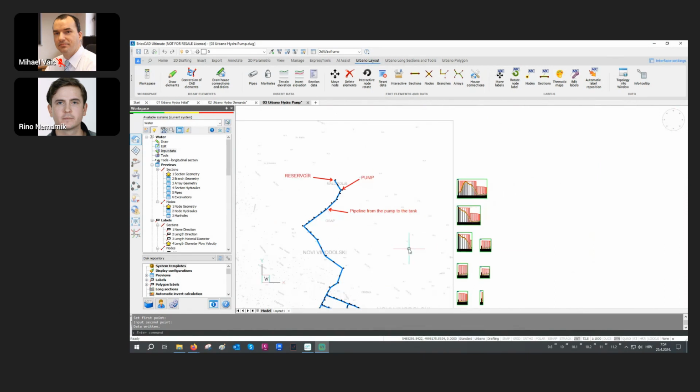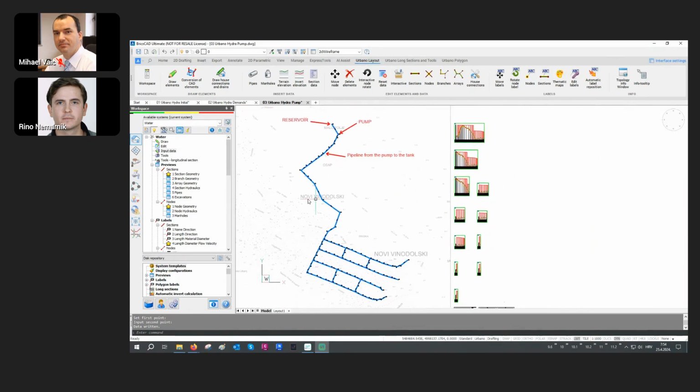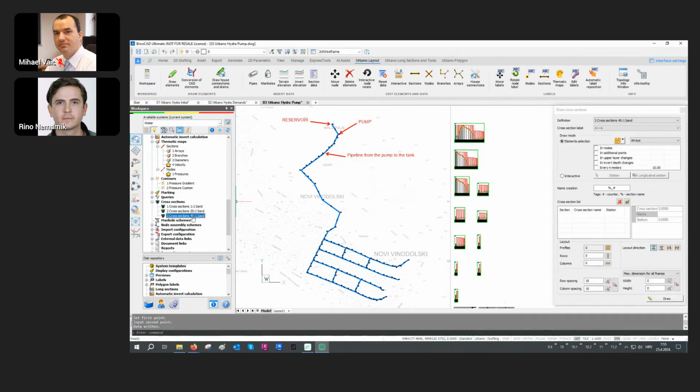This can also be seen very nicely if we draw some cross sections. And to draw cross sections in Softplan is really easy. Basically, just like drawing the profiles, you have your cross section configurations, and everything is stored in those configurations. From scale to colors to data to basically everything. So I will intentionally use this configuration in a little bit larger scale, 40:1.